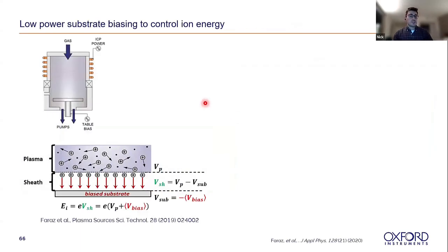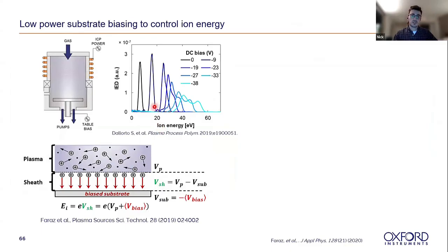Similarly, we want to use the low power attenuator because we want to get very low ion energies typically for ALE. As I mentioned, as you go to higher energies, you get this kind of spread. But at lower ion energies, you get more nicely well-defined ion energy distributions. And so by going to these lower energies, we can accurately land our ion energy distribution within the ALE window, and therefore, we're not going into that continuous bulk sputtering etch regime. We're staying nicely within our ALE window and getting very reproducible etch rate.